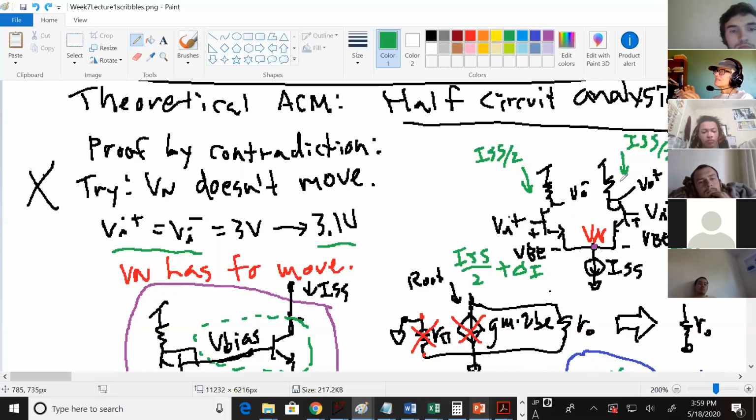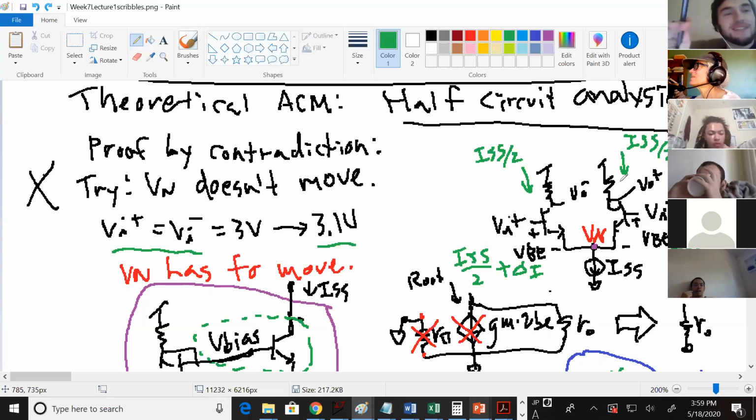And that actually has a special name when you cascode a diff pair. It's called a telescopic op amp because it kind of looks like a telescope. You've got the tail current source and then it goes out forever. And then what if you wanted super duper awesome, amazing gain? Gain boost it. Okay, so there are four flavors of this amplifier.